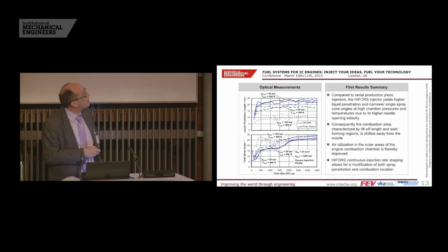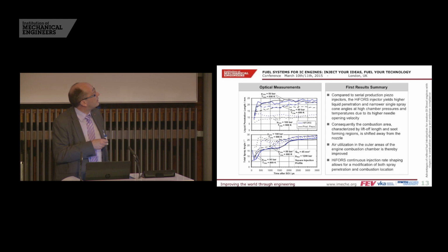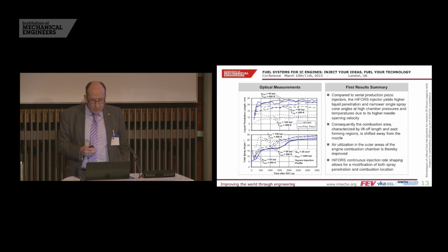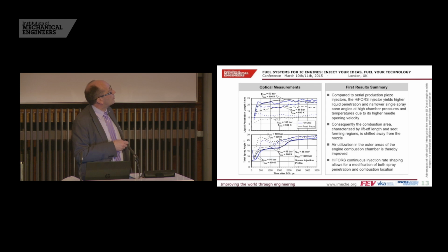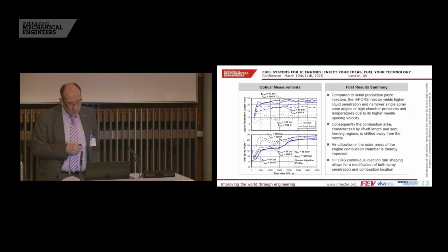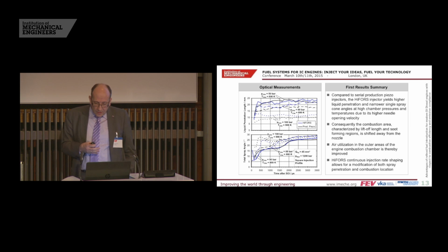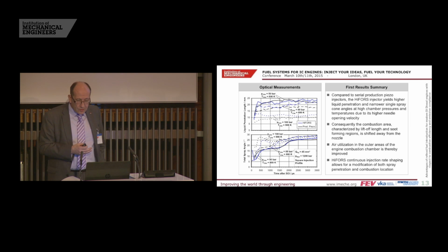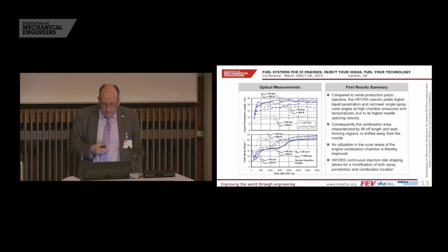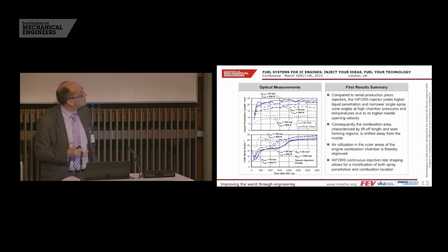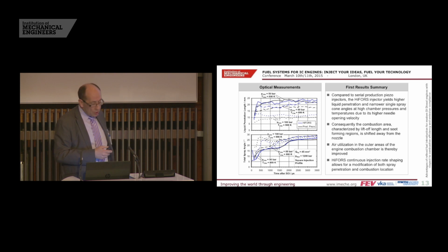We see that especially if we move into the region where we have quite severe boundary conditions, meaning high temperatures and high pressures, the benefits of the fast needle opening get more pronounced, and we get significant benefits versus the in-production piezo injector. So this of course means that by these conditions inside of the combustion chambers, the boundary conditions for a proper combustion are improved, and we can hopefully utilize this in better efficiency or better emission performance as well.